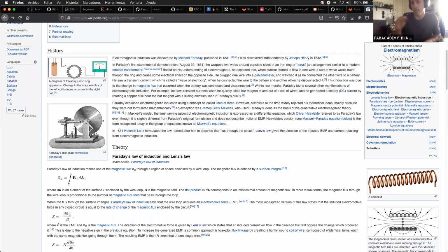You can use the energy that you are using to climb up the slope and then recuperate it when you go down, using your motors to put energy back into your battery. So that is broadly done. And yes, any motor can become a generator. The only thing that changes is the direction of the mechanical energy, let's say, if it comes out of the motor or if you put it into the motor.